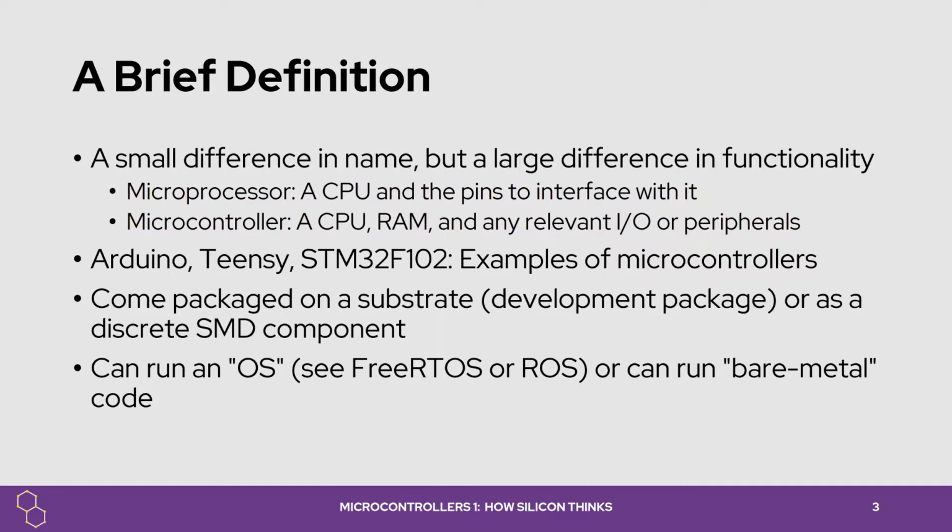The boards for microcontrollers generally come packaged either as a so-called development package, a dev board, or as an SMD component. Development boards are used where you want convenience and where you'd rather quickly iterate on your code, because they generally come with a USB interface to flash code onto the microcontroller.